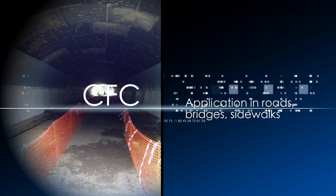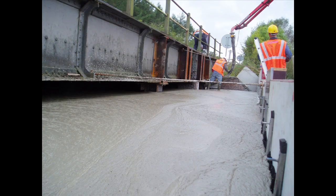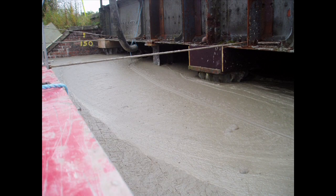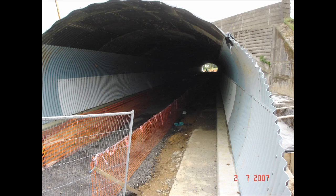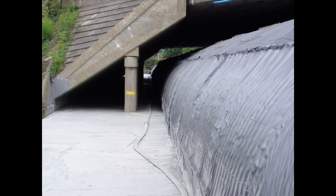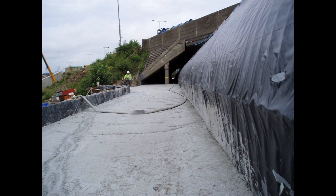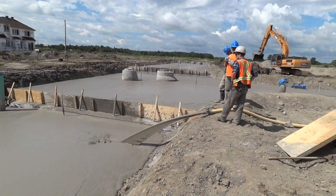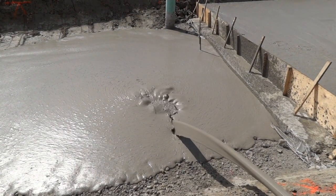Application in roads, bridges, sidewalks. It is a well-known fact that frost heaving, one of the main factors for destruction of roads, bridges, tunnels, and sidewalks, is caused by the capillary migration of water and its freezing at low temperatures. Weak grounds are another reason for destruction of structures. The long experience accumulated in Canada, the United States and England in the application of cellular concrete for construction of roads has proved its remarkable advantages.